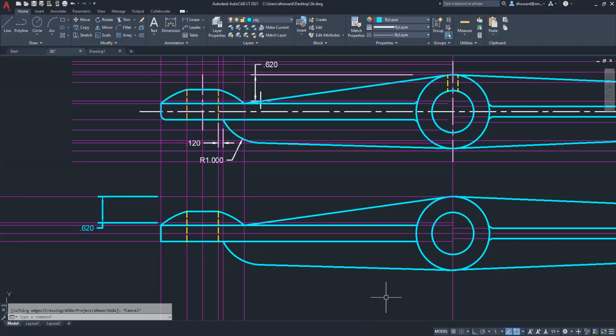All that remains is the fillets. So I go to my fillet command, get this guy here. And this corner over here, the upper portion is not filleted because it has been machined afterward. And so with a square edge, it's a machined surface.